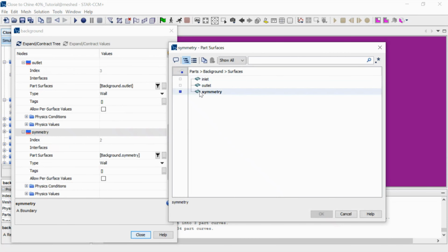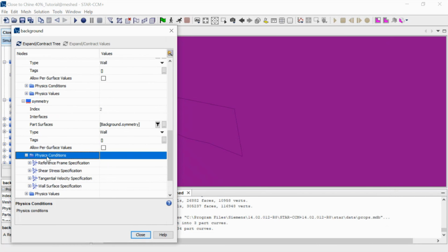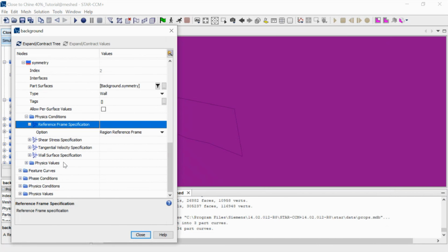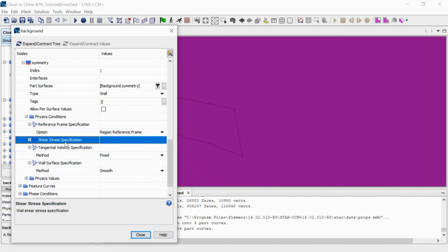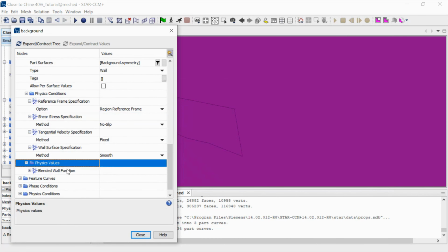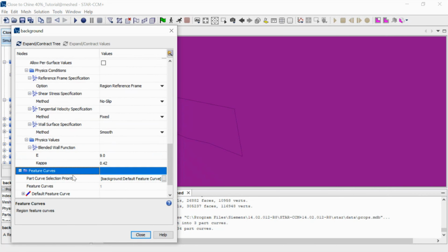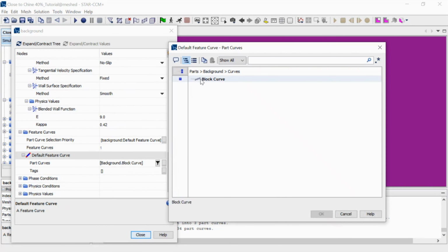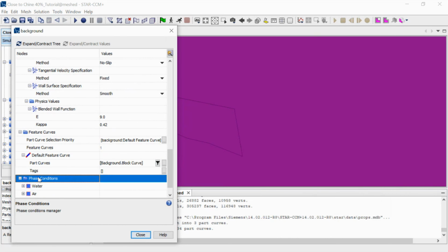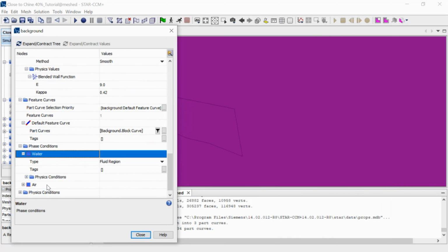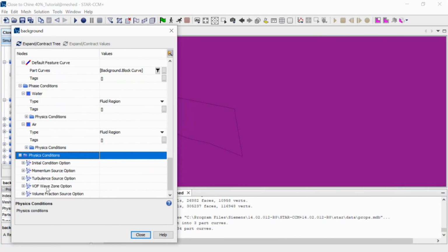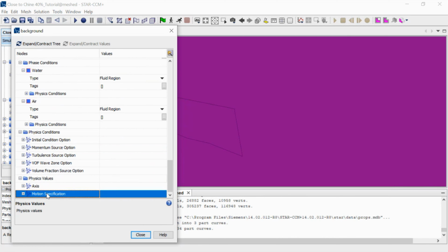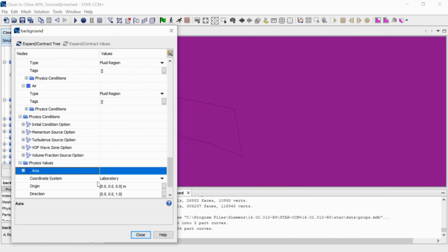Outlet condition: this condition requires no inflow from this boundary, so it must be placed far enough downstream to guarantee the stability of the computation. Otherwise, use zero normal gradient. Overset mesh creation is a bit more challenging than the one for a single mesh, since it requires the creation of two computational domains, the background and the overlapping domain. Regions are a fundamental aspect of setting up simulations, particularly in cases where you need to apply different boundary conditions, mesh resolutions, or physics models to distinct parts of your computational domain.